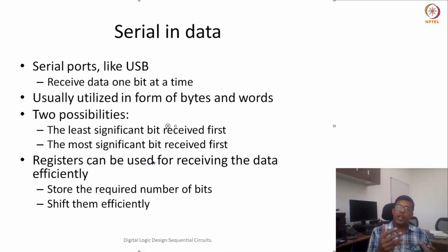So what has been seen, you can use certainly flip-flops. But the flip-flops have to be connected in a certain manner, since eventually we would like to store them in registers, and these registers have to be connected in a certain manner so that we can read them efficiently. They're being fed one by one, but we can read all of the data in parallel, like 32 bits of data at once, but they would be fed bit by bit.